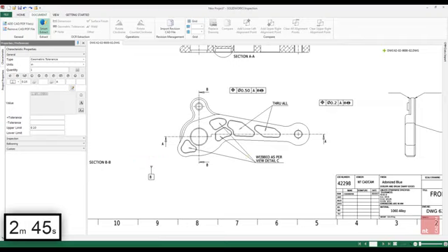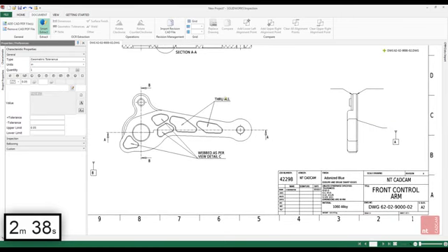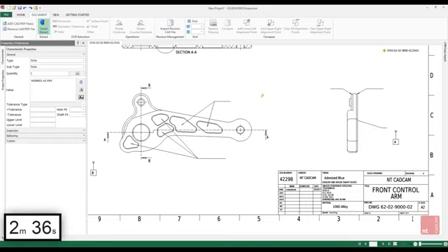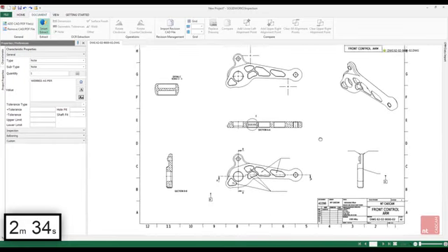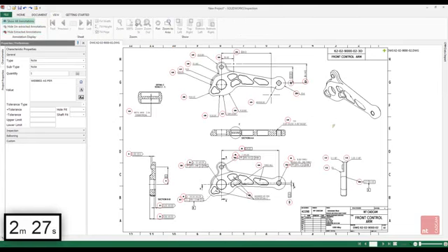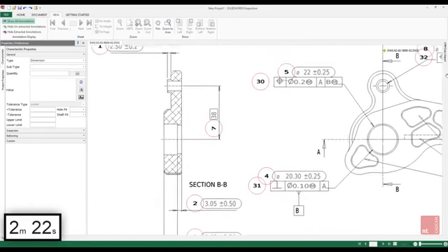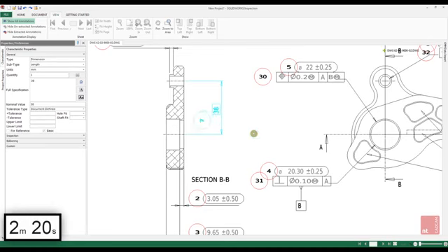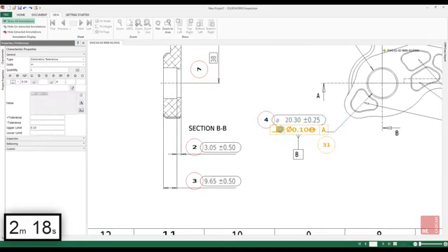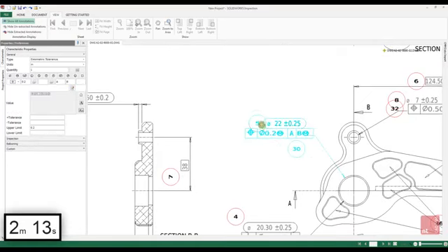Look at that, we even have the ability to accurately extract our geometric tolerances. And we can trust that SOLIDWORKS Inspection is extracting our characteristics correctly with no errors whilst calculating the upper and lower limits automatically. So now that we've extracted all of our characteristics, including the notes, we can now show all of our ballooned items. And in just 2.5 minutes, we've created a fully annotated ballooned drawing, where we've captured every single one of the characteristics and automatically calculated their upper and lower limits.